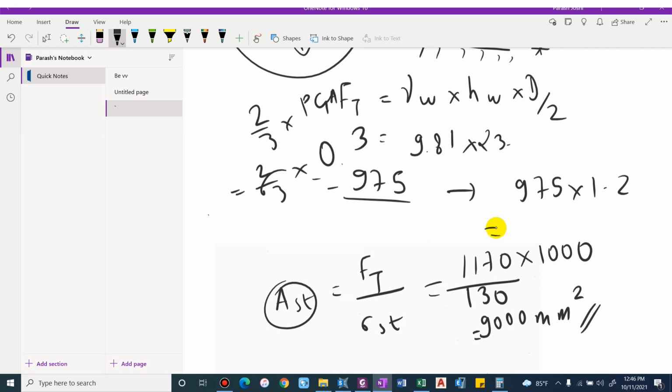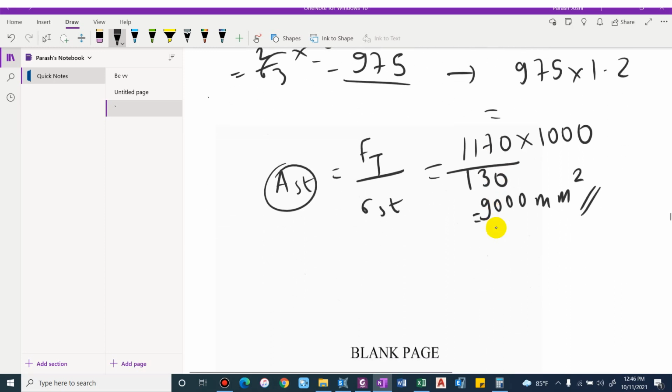Now we have to compute the thickness of concrete, or the thickness of concrete lining required. For this also we have to use a formula: sigma_t is equal to Ft divided by (Ac plus m Ast). Basically we are using the working stress method, so we have to use the modular ratio here. I already explained the modular ratio in a video related to analysis of crack width. You can go to the description, find the link and understand about the modular ratio and why we are using it.